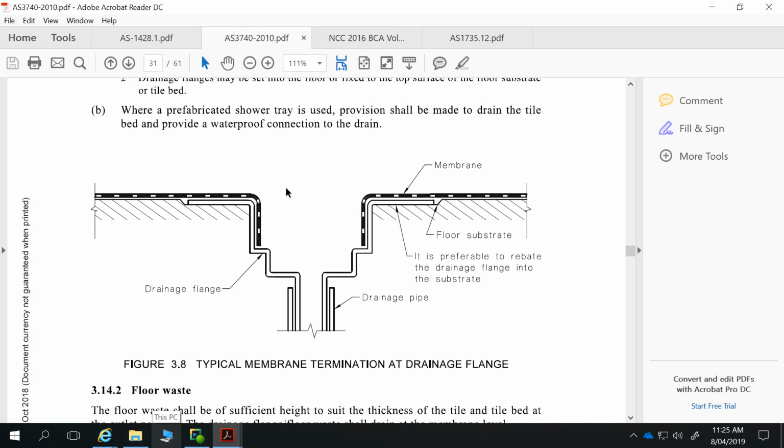So for our wet areas, we've got our layouts from Revit, so that's fantastic. If we're going to be modifying those significantly, then we refer back to the clearance spaces in AS 1428.1, and then we do all of our waterproofing details as per an unenclosed shower. That means our water stop being a minimum of 1500 millimeters distance from our shower rose, and waterproofing of that entire floor up to that water stop.